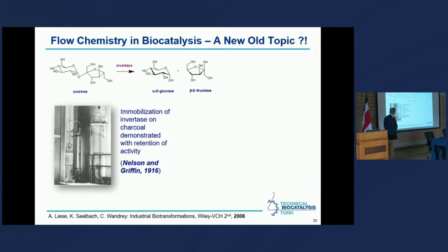They didn't have a pump, so they just put the water with the sucrose on a higher level and let it flow by gravity through the column. You always let it flow from the bottom to the top in this operation, because if any bubbles formed in there, they are drawn out to the top and not trapped. And this was an academic publication.